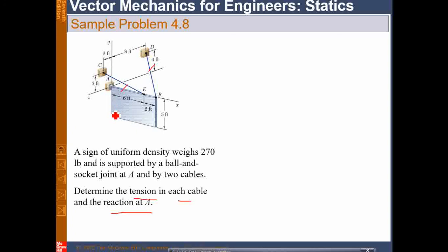So as we have seen in statics, we use force balance and moment balance. Just look at this problem. As you can see, the first step is to make the free body diagram. Now at location A, this is a three-dimensional problem, fixed support. So we will be offering three reaction forces along the x, y, and z directions. Another thing, this tension component here is again lost in space.